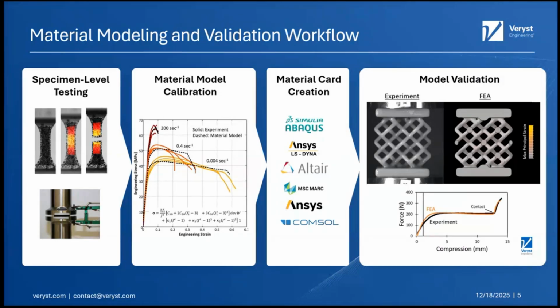So do you recommend to lubricate the test to rule out friction as much as you can? So generally, yes. And I do this both for compression tests as well as that indentation test that I was showing. Mostly because I would like to reduce friction as much as possible because that makes my life easier. Other people will take the other approach where you want no slip.